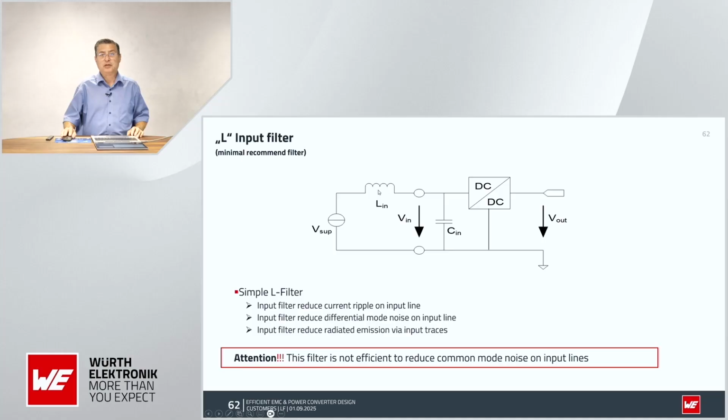So you cannot put a very high impedance or a very high millihenry inductance here, because this ferrite bead is acting like an inductor, and it will slow down the current. You cannot put more than maybe 1-2 microhenry inductance here, else the capacitor on the input will starve. It won't be charged in time.